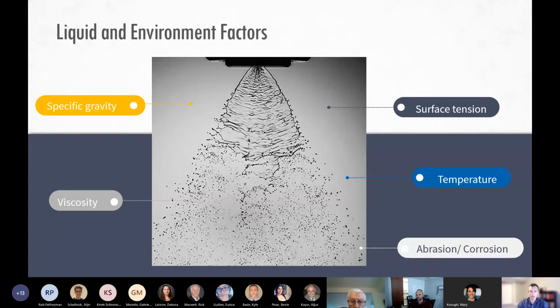Surface tension often has a similar effect where it resists the breakup of the droplets. However, surface tension is going to be a little bit different in that the viscosity will sort of have a slow effect on changing the droplet size or the spray characteristics, whereas surface tension we typically find has more of a cutoff level where once you reach a certain pressure, for example, with a flat spray, you can start to see droplets not atomizing well at all, and then all of a sudden bursting into smaller droplets. So the effects of surface tension versus viscosity tend in the same direction. Higher surface tension, higher viscosity lead to larger droplets typically, but the end result on the spray atomization can be quite different.